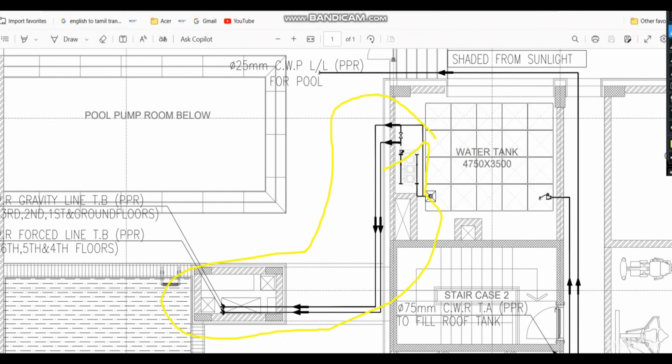Even after providing aluminum cladding, the client wants the aluminum tray cover too, because sometimes in our project we have a swimming pool and this arrangement, so the people are walking here and there. The pipes should not be visible from the visible end, so in this project we provided the aluminum tray cover throughout the pipeline like this. So the pipe is not visible from outside. Even a child cannot walk over the pipeline and damage it. So this is the reason we provided it.